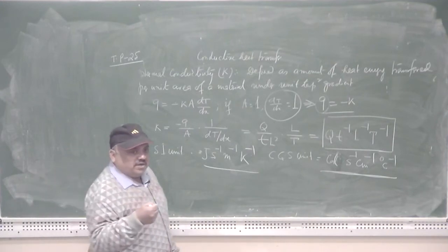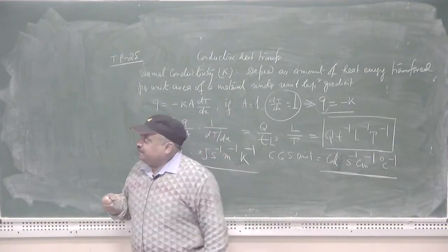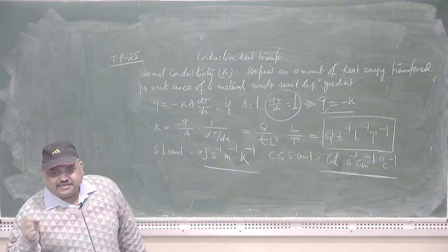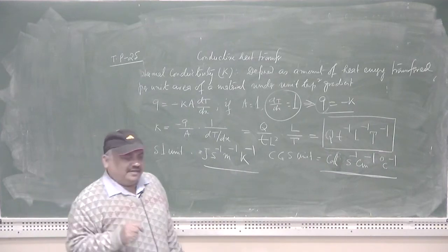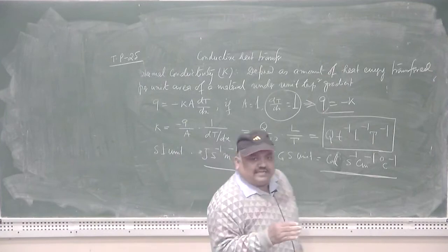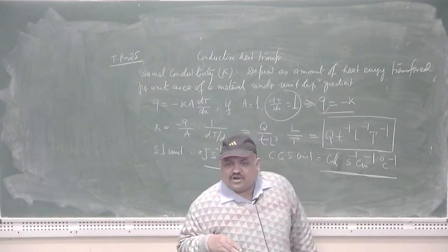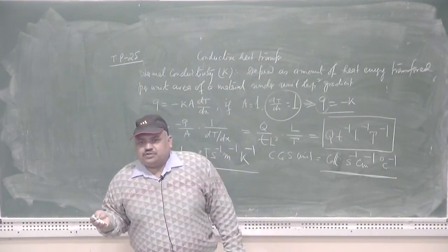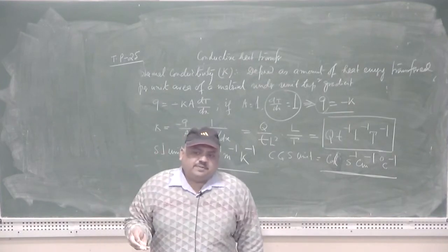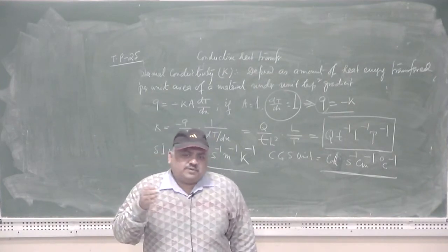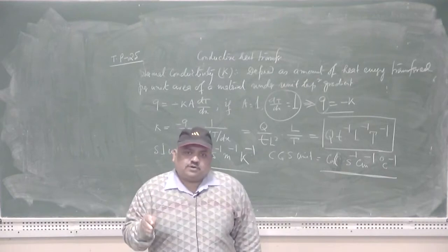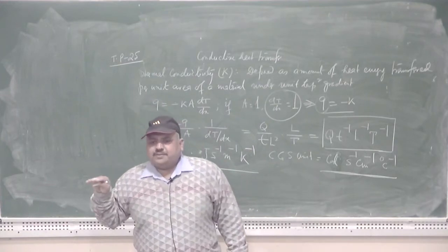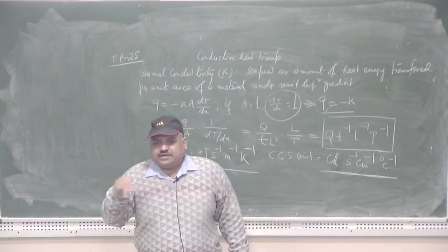Once you have poured the liquid metal in a mold, it has a certain amount of associated energy, which it achieved during the course of melting. So, that heat energy needs to be dissipated in order to get it solidified. Depending upon the mold material you have chosen and its thermal diffusivity value, the amount of undercooling experienced by the liquid metal during solidification will be different. At a higher undercooling, more and more particles may get nucleated from that liquid metal.